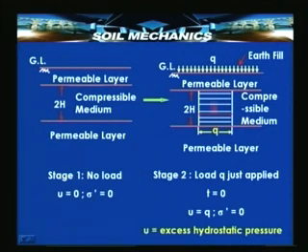See here, when there is no load, there is no pressure in the compressible medium. The moment we apply the load, that is, we are applying Q in the form of a surcharge, then the pore pressure distribution in the soil is uniform with depth, and it is equal to U. So, that is why we have written u is equal to Q and sigma dash is equal to 0.